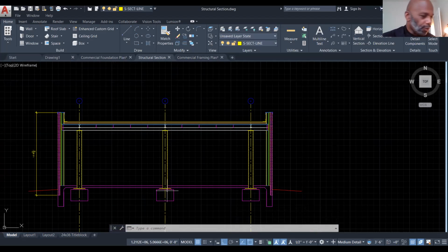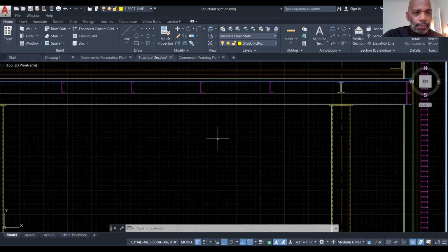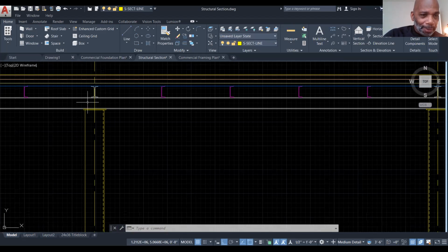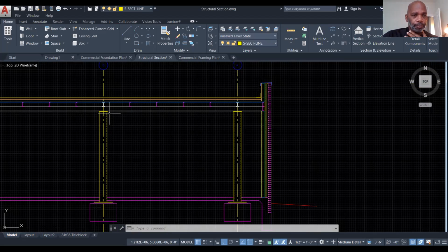All right, so I think all that you have to do now is follow the sample drawings and start to add the notes and the dimensions. Of course, here you need to add the splice plate that joins these two members together, and you can get that splice plate from the framing plan of section C. So we need a splice plate here.